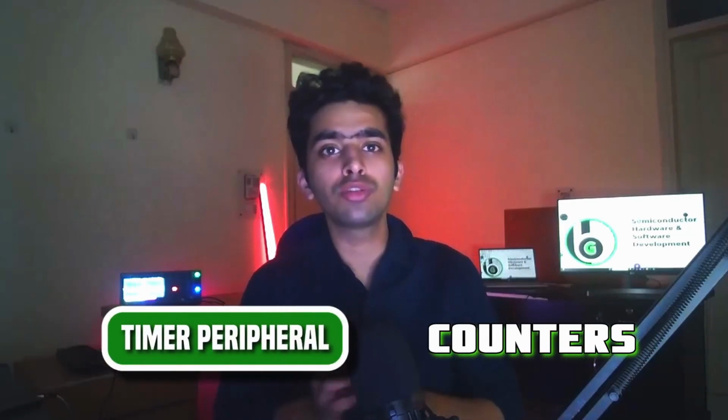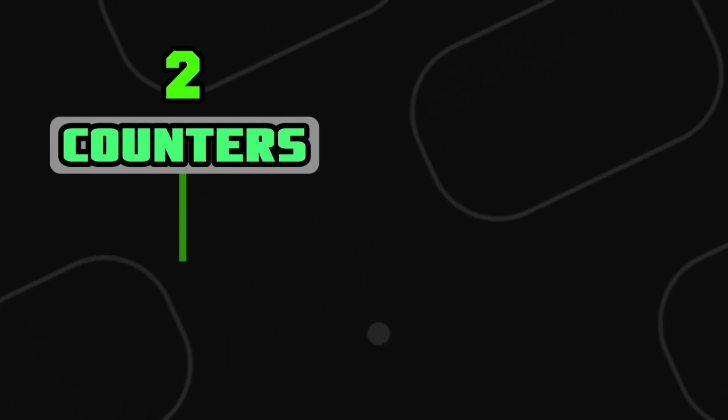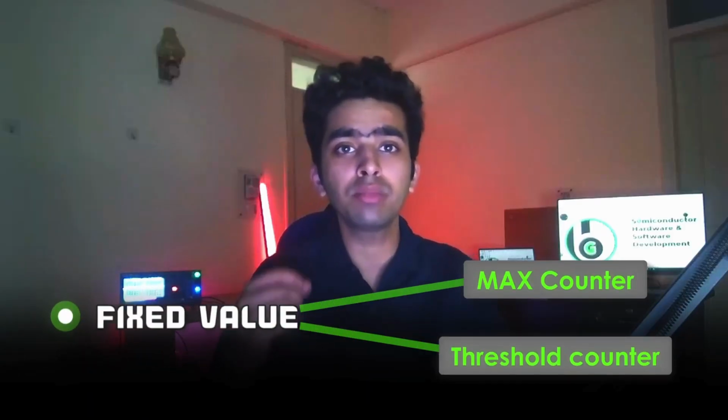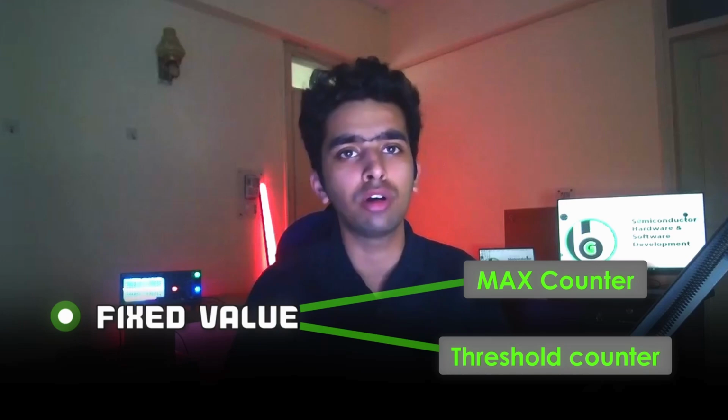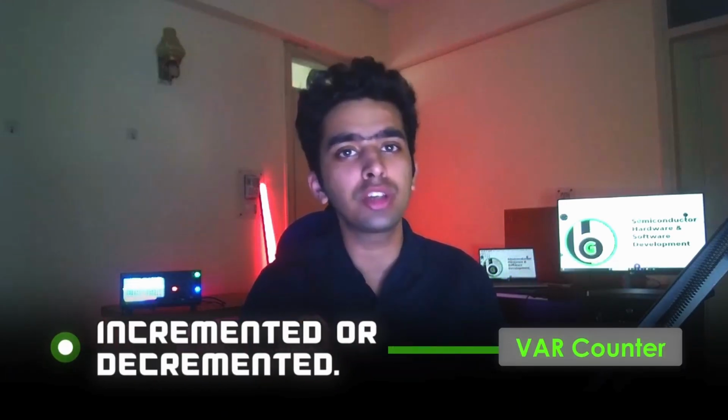The timer peripheral has a concept of counters, and there are generally three types of counters in the timer peripheral. Two counters have a fixed value and one counter would be incrementing or decrementing. Let's name the fixed value counters as the max counter and the threshold counter, and let's have the last one as a var counter, which would be changing its value.